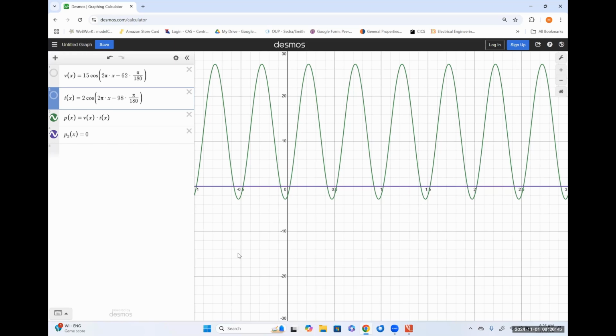This is something that we're going to talk about when we're talking about complex power in a couple of days, and about inefficiencies and things like that in the system, because this represents effectively power that's being generated and then being sent back to the source. All the inductor or a capacitor can do is absorb it and then give it right back, okay? Sounds like a waste, but without that, our electricity grid would not work. Okay, so anyway, we'll talk about that more in detail in a couple of days.